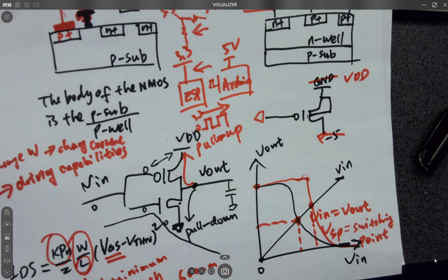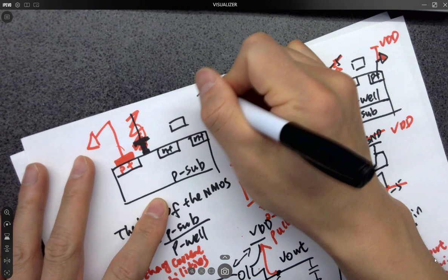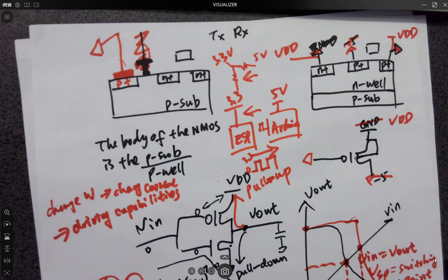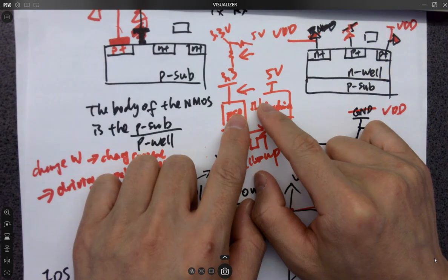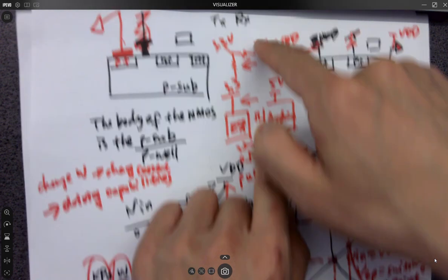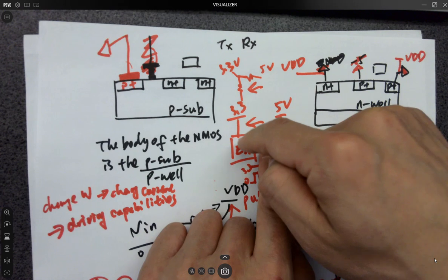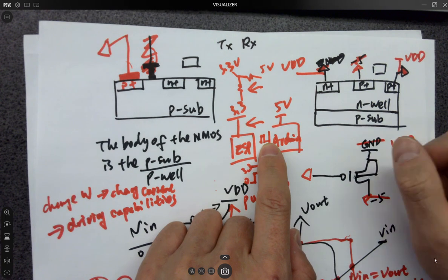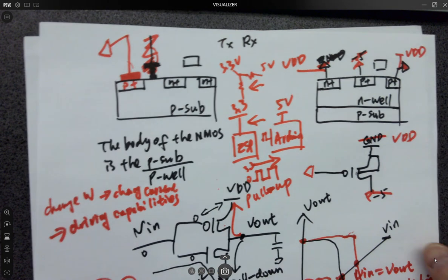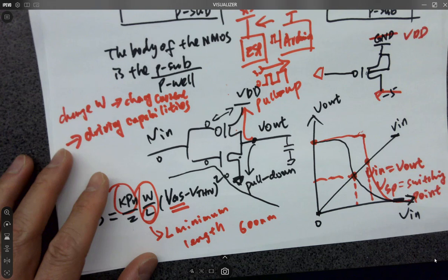So one direction from ESP to Arduino is okay, but for the other direction, because a lot of times the communication is bidirectional, right? Like all these TX and RX for UART, SPI, I2C, whatever. So they are all bidirectional. So in that case, whenever it's a transmitter node to a receiver node to the ESP, you need a voltage divider in the middle. Keep in mind, otherwise it's going to damage the ESP in a second. Whenever you power it on, done. Make sense? Okay. Question on this?